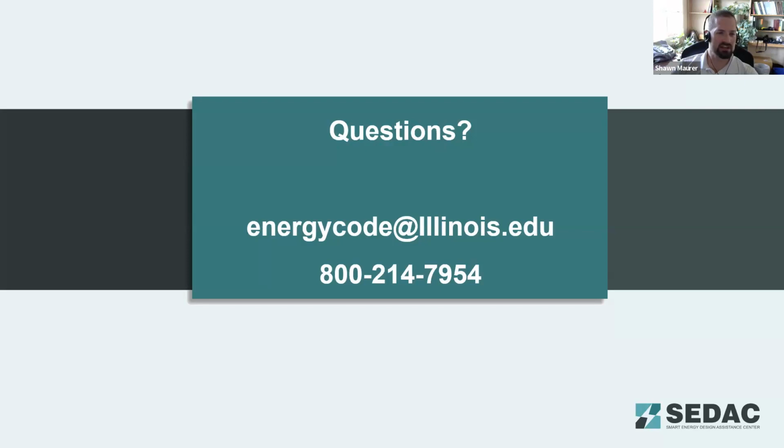We had something in the chat, just clarifying our alteration to the low slope roof question. They wanted to make sure on a low slope re-roof project, replacing just the membrane, not the rigid insulation, you would have to evaluate and possibly increase the insulation. So yes, if you pull the membrane off the roof and you expose the insulation or roof deck underneath, you would have to, for insulation above deck, increase that insulation level. There are possibly some limitations that would limit how much insulation you can add to that roof. And so you would add as much as you can given those existing limitations.